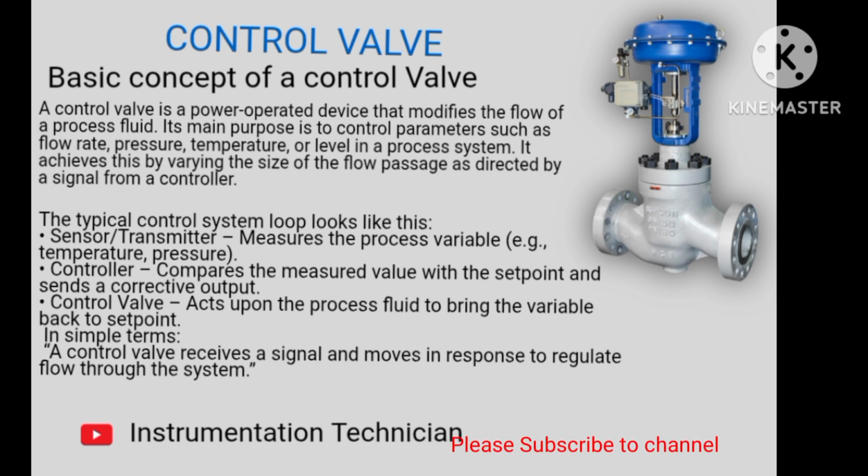The typical control system loop looks like this. Sensor, transmitter: measures the process variable, e.g., temperature, pressure. Controller: compares the measured value with the set point and sends a corrective output. Control valve: acts upon the process fluid to bring the variable back to set point. In simple terms, a control valve receives a signal and moves in response to regulate flow through the system.